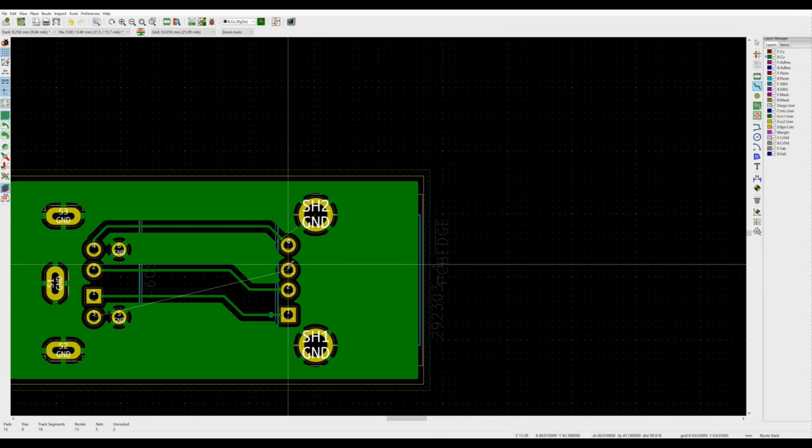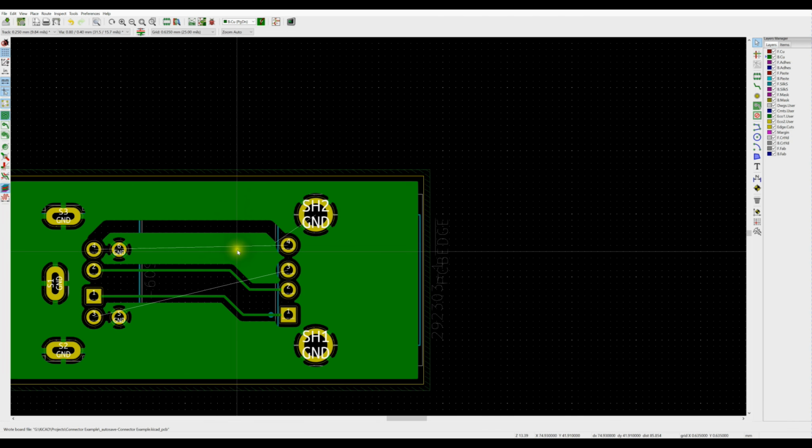I really hate it, I've got a ground here that's unhappy as well. So we're going to run a double-sided board. So let's go ahead and delete this guy out. And let's reflood fill. That reflood fill will get this connected back to here.